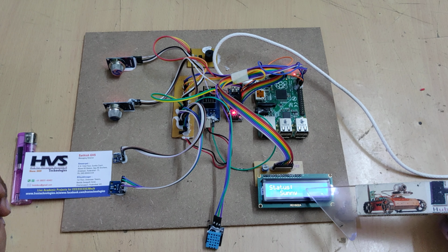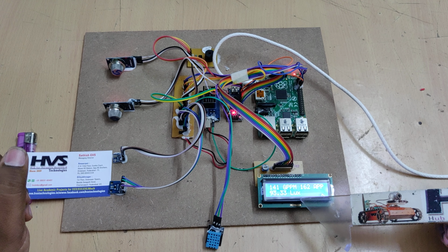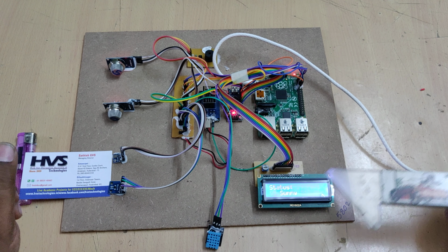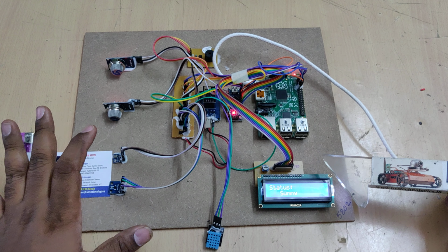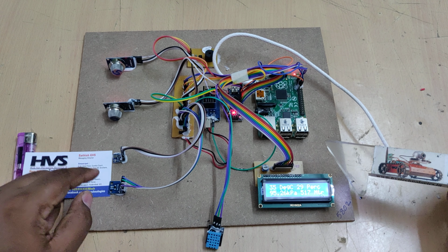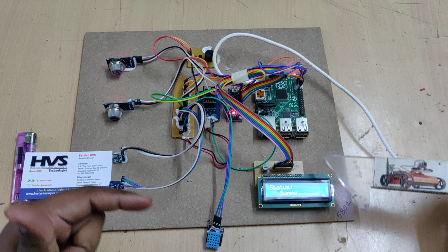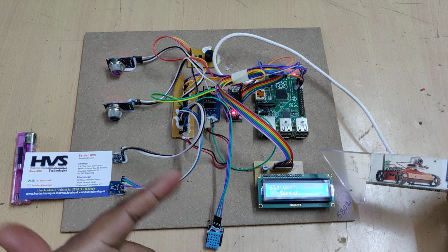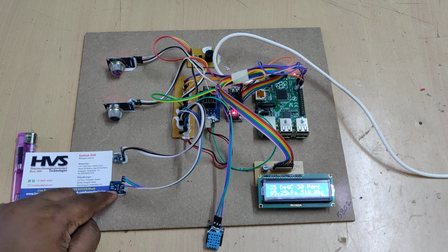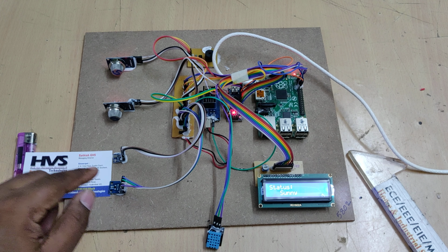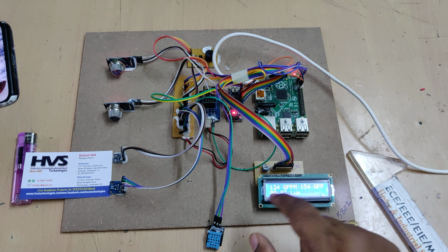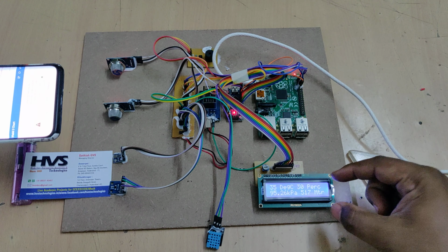So right now, the data is collected with the Raspberry Pi, and the decision was made, and the prediction displayed on the LCD. The status is going to be sunny. As of now, everything is normal. If any abnormality is detected from the humidity or light, so when the humidity is more, temperature is more, it is normal only. If the humidity is more, temperature is less, it's going to be cloudy. Based on the sunlight intensity also, the decision will be taken by the Raspberry Pi with the help of decision tree algorithm.